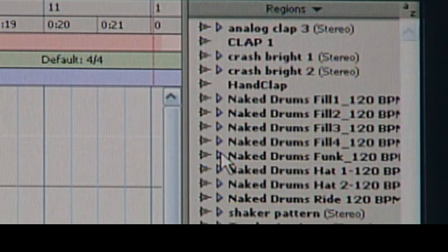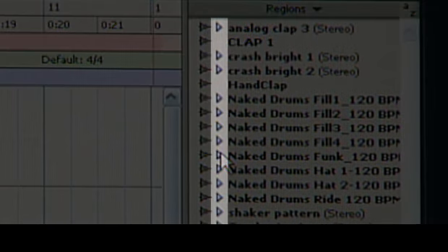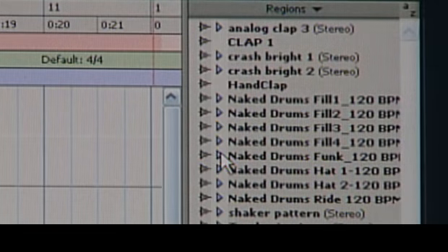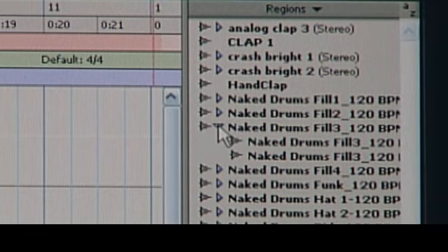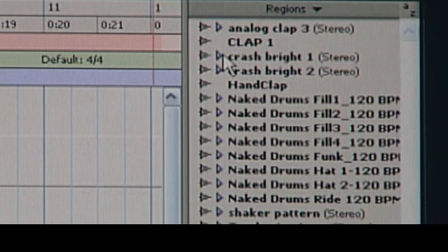Notice the triangle next to the audio file names in the Audio Regions list. This indicates they're multi-channel. We can click on the disclosure triangle to reveal the individual mono files. Pro Tools works with multi-mono files, not stereo interleave files. We can import stereo interleave files, and Pro Tools will automatically create the left and right sides for us. We can also generate stereo interleave files. Most CD authoring programs require this. We'll look at that when it's time to mix down.